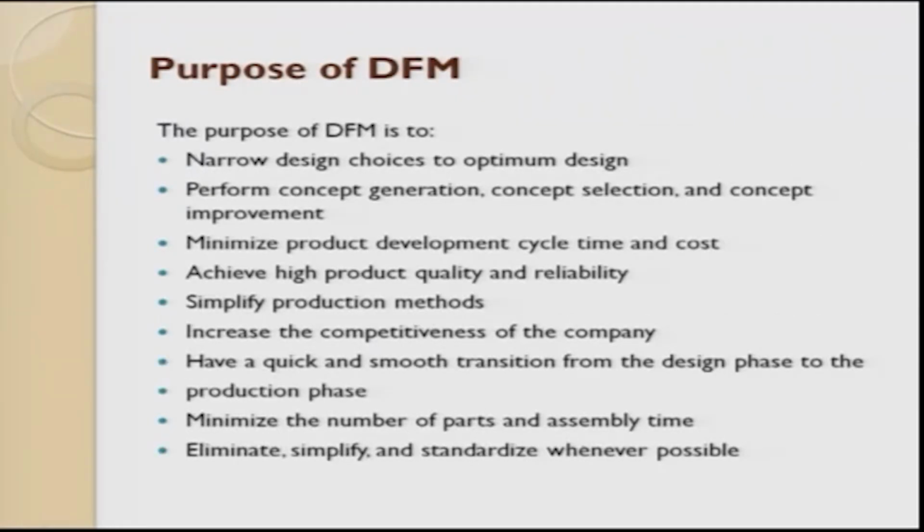The purpose of DFM is to narrow design choices to optimum design choices. Narrowing of design choices is very important, because if you give a wide variety of choice, we will not be able to solve the customer requirement problem. So it is always good to narrow design choices, and within them you can always look for the optimum design.